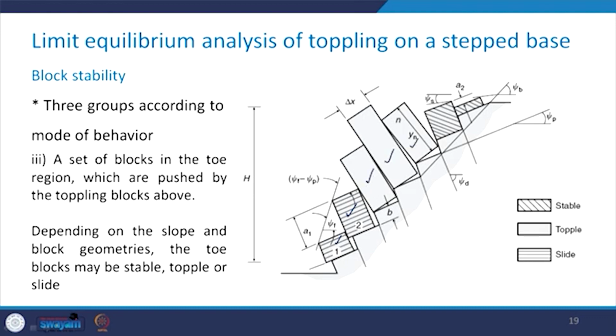So, these will push these 2 blocks lying in the toe region, and therefore these will experience sliding. Depending upon the slope and the block geometries, the toe blocks may be stable, they may topple, or they may slide.